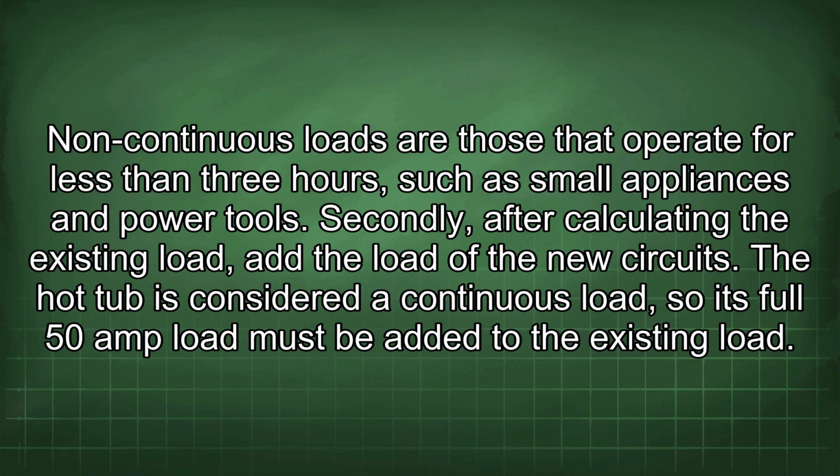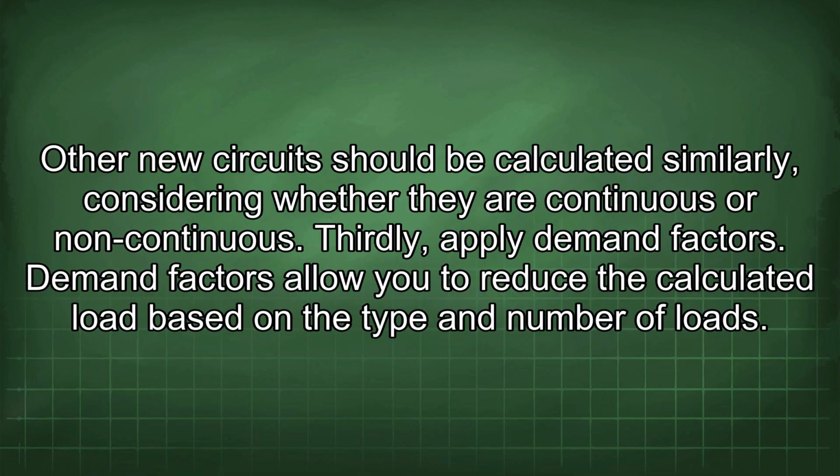Secondly, after calculating the existing load, add the load of the new circuits. The hot tub is considered a continuous load, so its full 50 amp load must be added to the existing load. Other new circuits should be calculated similarly, considering whether they are continuous or non-continuous.